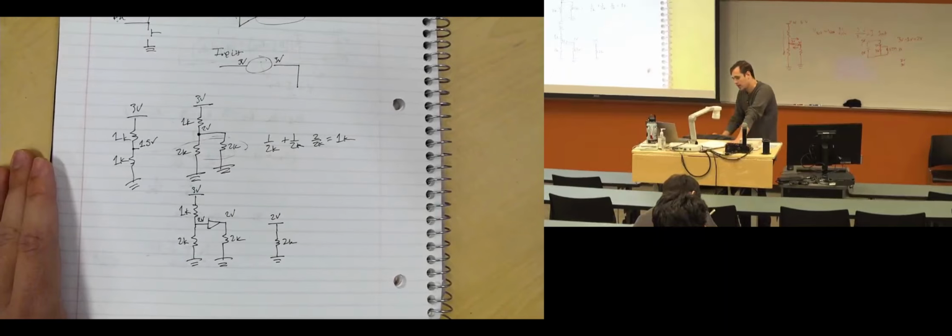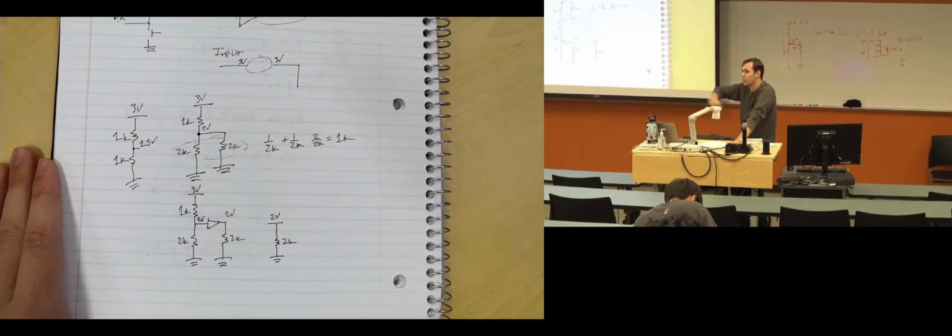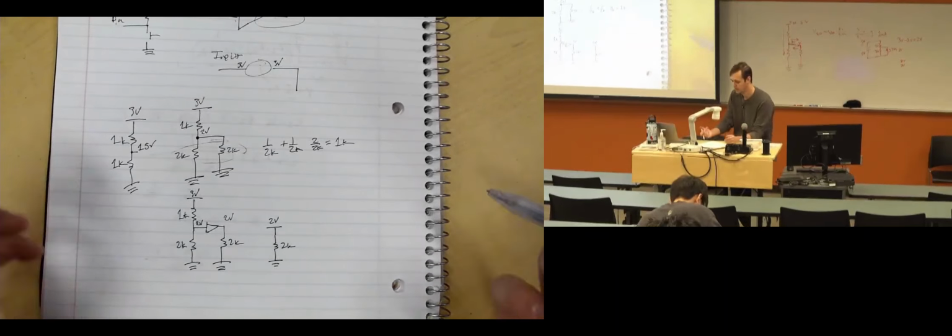By giving a digital value of 0 to your DAC, you can output 0 volts on whatever pin, or if you give it, it'll make sense later, 8,191, it'll output 3.3 volts. And you can do anywhere in that range. So it allows you to control it like it's analog, but digitally.